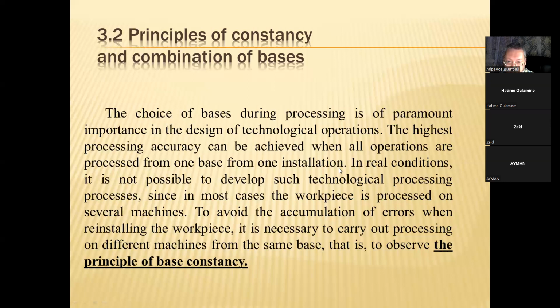To avoid the accumulation of errors when reinstalling the workpiece, it is necessary to carry out processing on different machines from the same base. That is to observe the principle of base constancy. So why do we use the principle of base constancy?